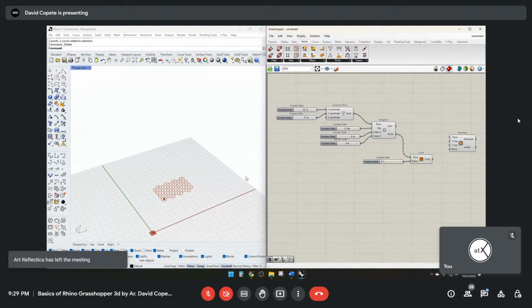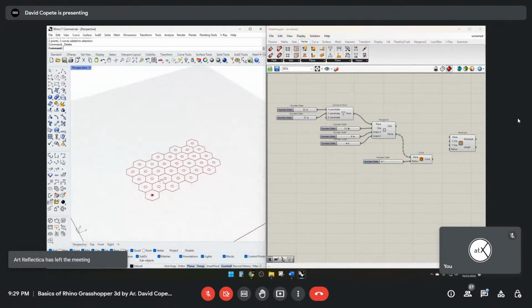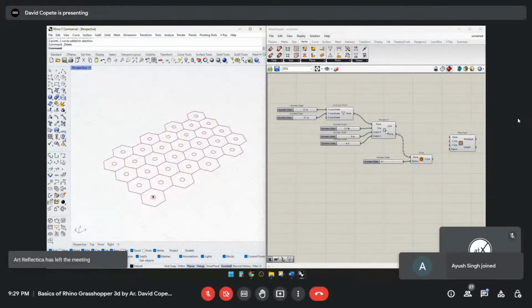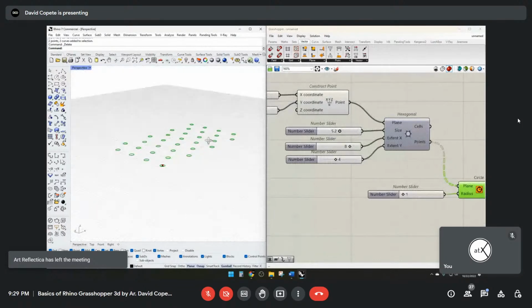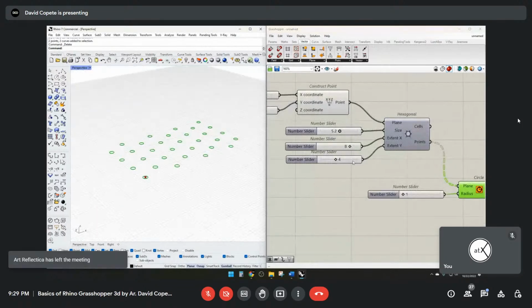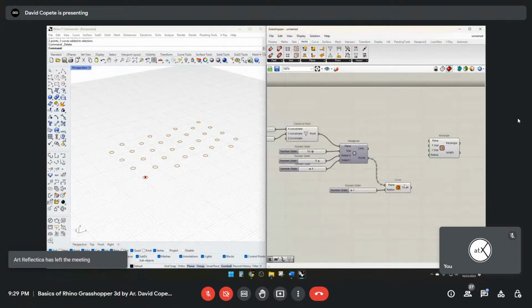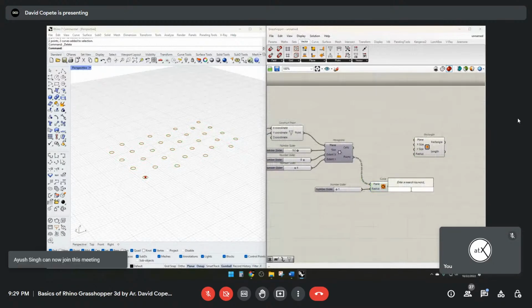Now, we don't necessarily have to preview geometry. This could just be how I want to organize my columns. So I can take this, right-click, disable preview, and now all we have here is nothing more than an array of circles that we can now turn into surfaces. How?